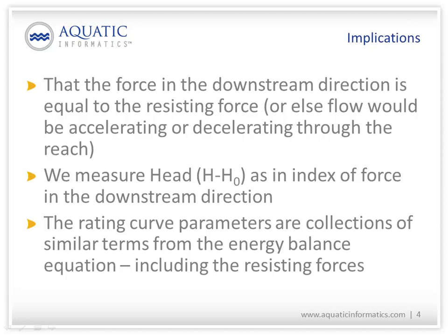Our assumption that we can relate stage with the total energy in the stream tells us what that downstream force is, and then we can make observations about the channel configuration to understand the resisting forces, and we can develop an understanding of how those resisting forces will change as a function of stage, and how those factors affecting the channel resistance can be lumped into our rating curve parameters.